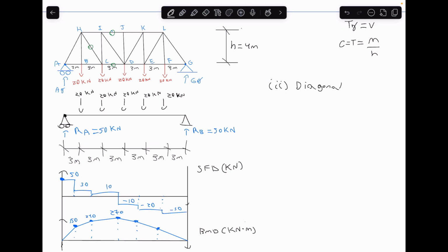So step 3 is to find the axial force in the diagonal. Now we've made the single diagonal assumption. So we determined that, okay, pretend this is a panel. There's only one bracing and it's in tension. And we have some shear force acting vertically like this. Therefore, the y component of that bracing is equal to the shear force.